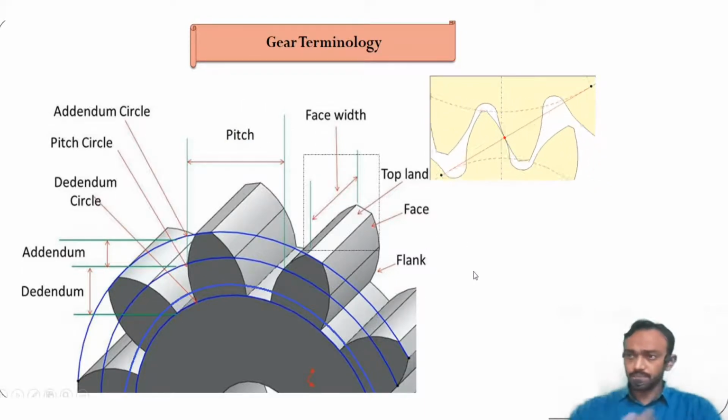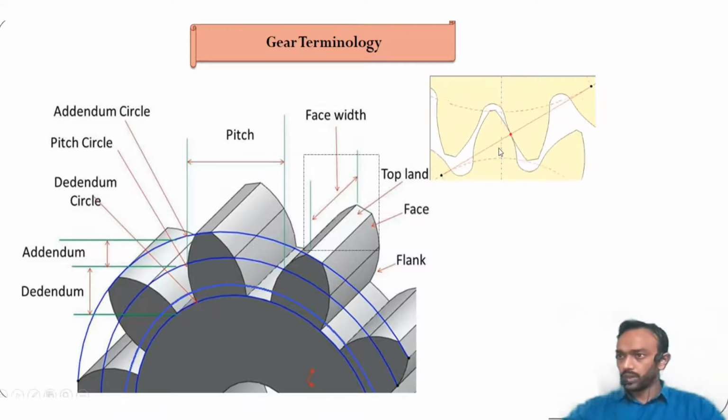And you can see in this animation we have kept some clearance. First clearance you can see here at the bottom, so the top of the teeth does not undercut the bottom here. And the second clearance you can see at the side of this tooth. It is known as backlash. The side clearance we kept is known as backlash, and the bottom clearance is known as clearance.